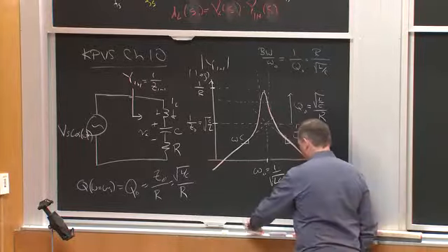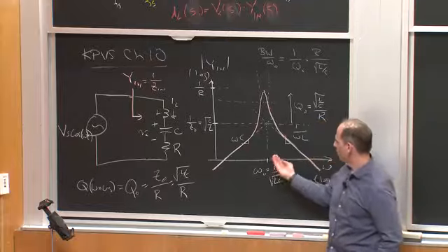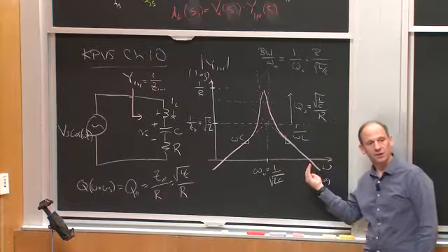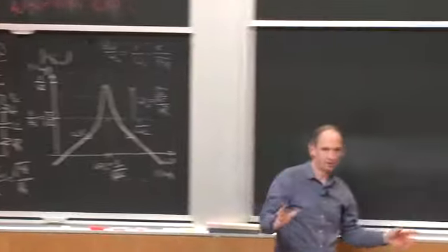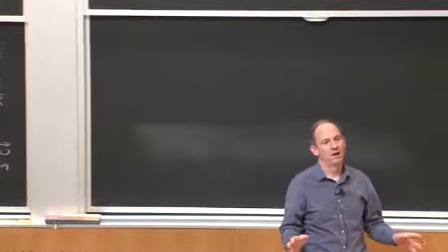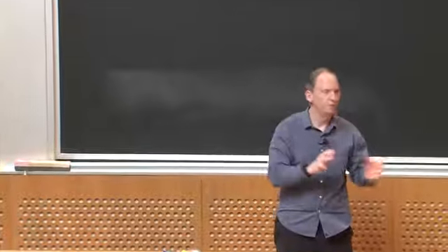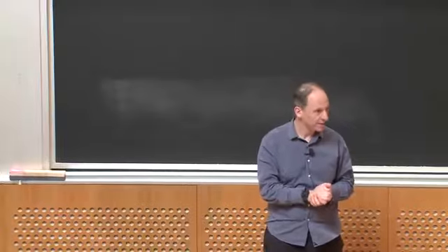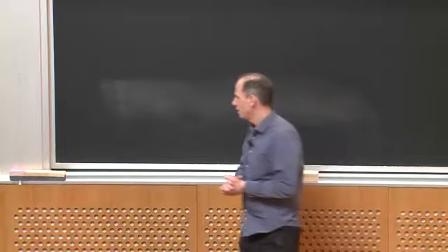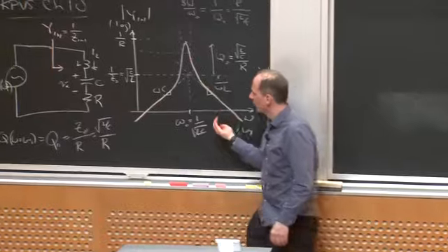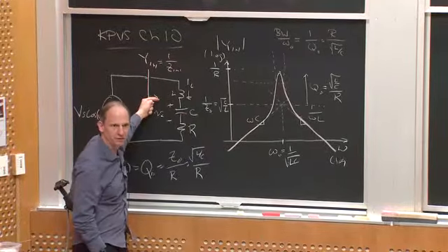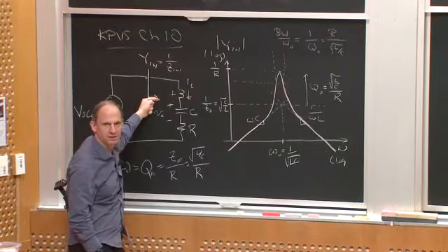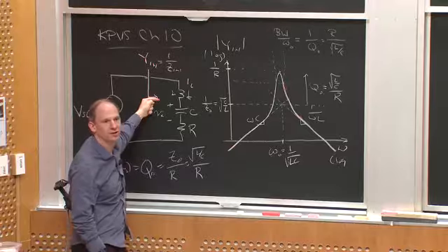All right, well, what would I choose to do? Very often, what we're going to do is run this above resonance. Okay, at least for modern devices. And when I talk about resonant converters, they don't have to be soft switched. But frequently you choose this kind of approach because you can make it soft switched. And if we operate above resonance, okay, is the input admittance look inductive or capacitive? Or the input impedance, does it look inductive or capacitive?